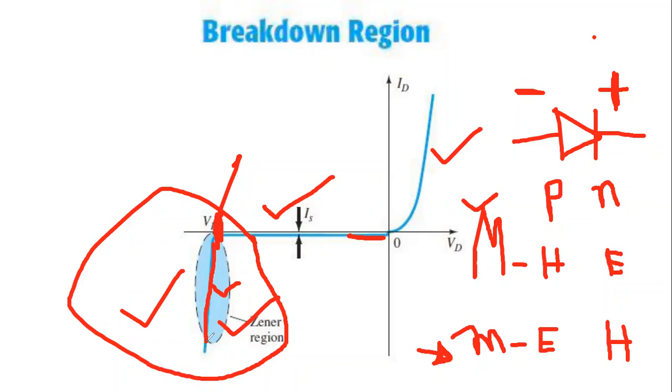And the important thing is, sir, can a normal diode or normal doping make a Zener region? No. You need the semiconductor material highly doped. Highly doped means the ratio in which we dope the P type and N type, with antimony or boron, needs to be much more than the amount of doping we do normally. So highly doped semiconductor materials are basically converted to Zener diodes.